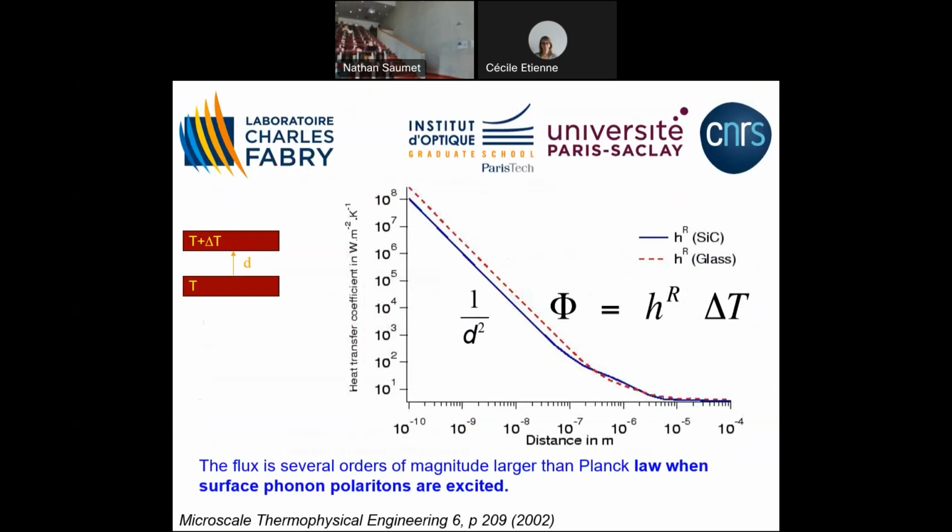Because what kills you, if you have in mind the Shockley-Queisser thermodynamic limit of efficiency for photovoltaics, is the fact that you are absorbing with a given band gap, but the incident photons are the solar spectrum. So a few of them have the right frequency. Most of them have a lower frequency, and you do not absorb them. Or they have a higher frequency, and you lose the excess energy. And if you do the best you can do, you end up with 33% conversion efficiency. Before you start, you cannot do better than 33%.